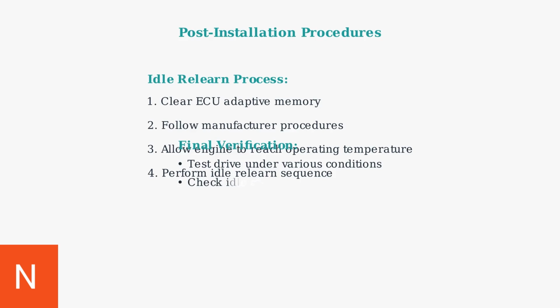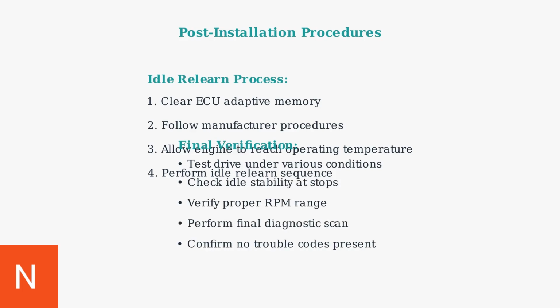Complete the process with a comprehensive test drive under various load conditions, followed by a final diagnostic scan to confirm no trouble codes are present and the system is operating correctly.